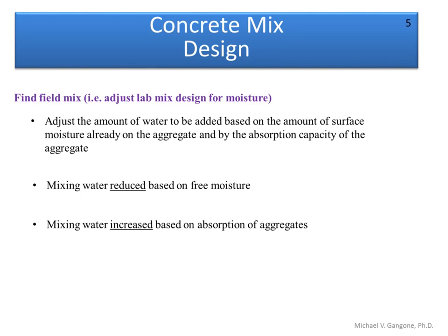All right, I kind of mentioned this already. We have to find or adjust the mix. So again, when you're going through the process of a mix design, the very last stage is to adjust for free moisture and for absorption of the aggregate. And we talked about the importance of this previously in one of the earlier slides.